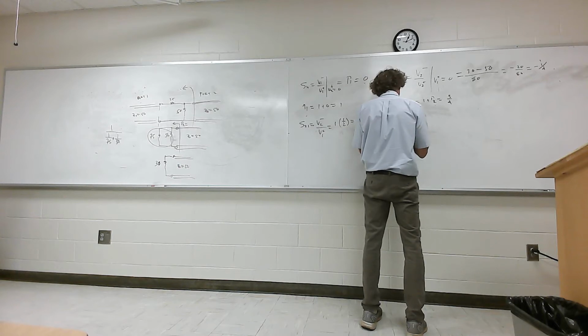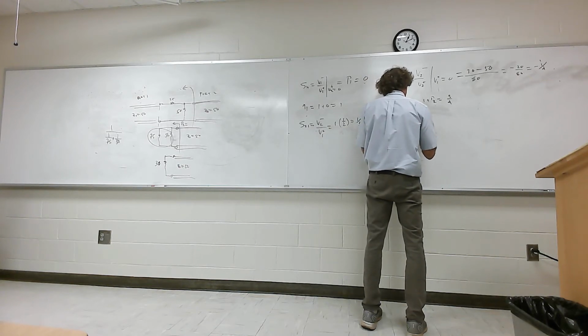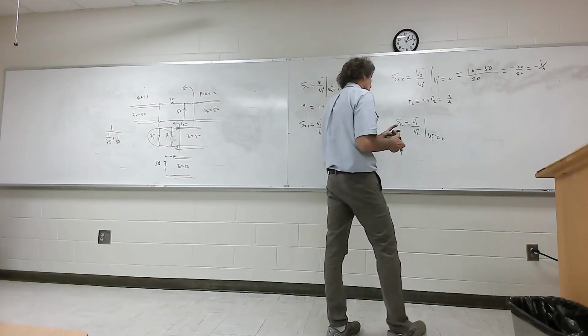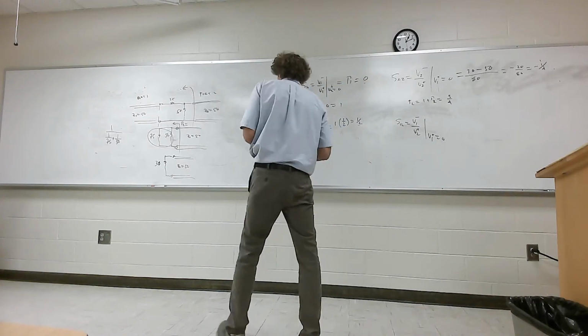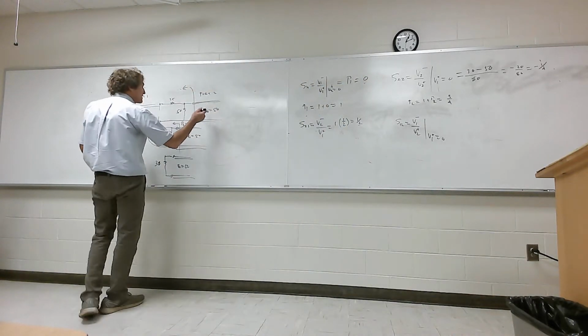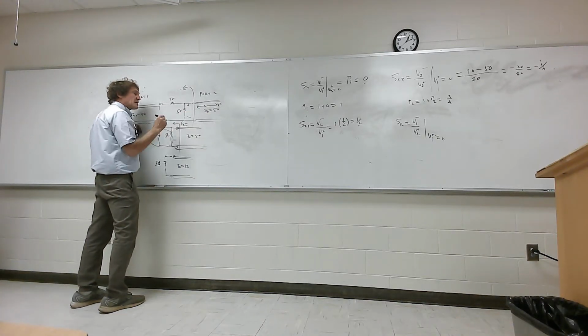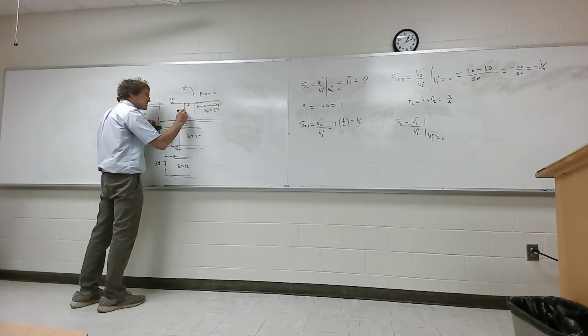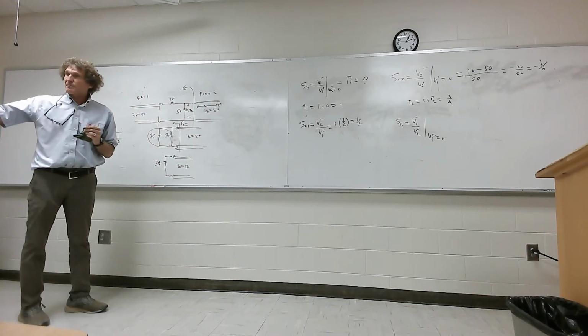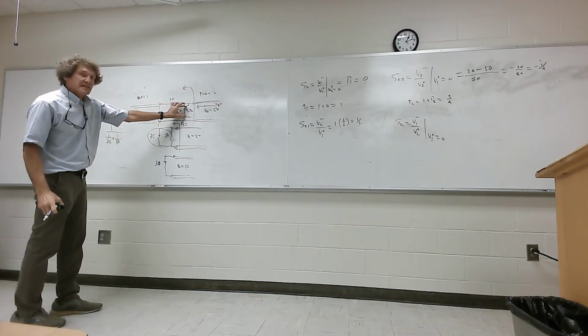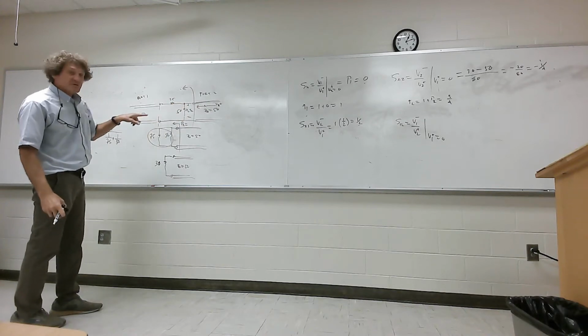Okay, now, when I want S21, think about it. That's S12, which is V1 minus over V2 plus, assuming V1 plus is 0. What's that actually going to be? Well, now I take a look at this. If I have a wave coming this way, and this is my V2 plus, the amount of that developed right here is going to be V2 plus times the transmission coefficient, right? Y'all follow me on this? Can y'all see it back there? All right, now of that, how much is developed over here? Well, I use voltage division. I take 50 over 75 times that.